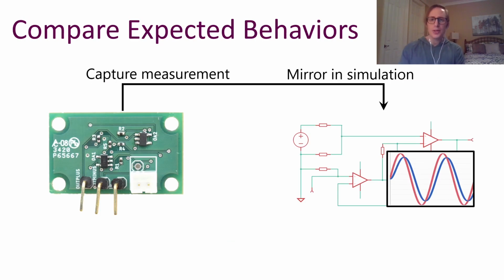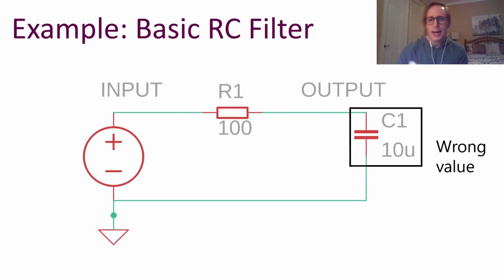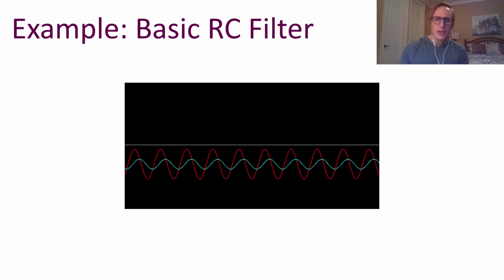At the highest level, the first thing that Pinpoint enables is comparing live measurements from the hardware with the expected behavior as predicted by the simulation. As an example, imagine you have this very simple RC filter circuit, which attenuates high-frequency noise. Suppose we have a fault and the capacitor's value is outside of tolerance. When we hook up the circuit to an input, here a sine wave shown in red, we can see that the output, in cyan, is attenuated. But is this filter working correctly according to the parameters of our design?